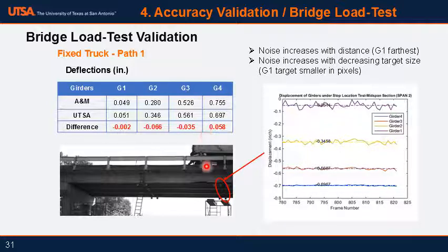Another place where we win out is that even after 2 days or so of installing instruments, they were only measuring at certain locations. Whereas now, because we're using the camera system, anything that's in this field of view can be measured. We can select the target here, we can select the target on the concrete, we can select the target here on the pier. So anywhere you want, you can measure. So that is also another very big advantage of the system.